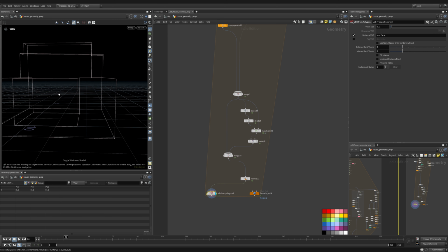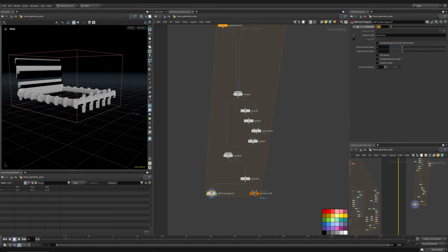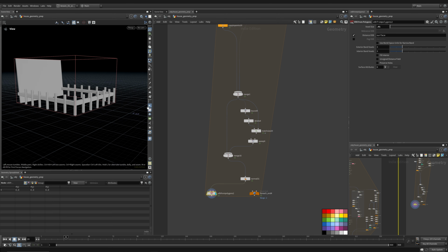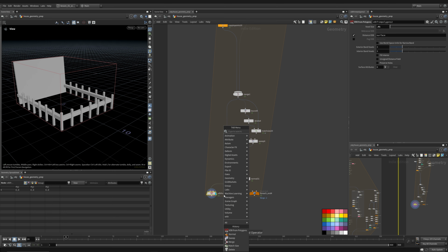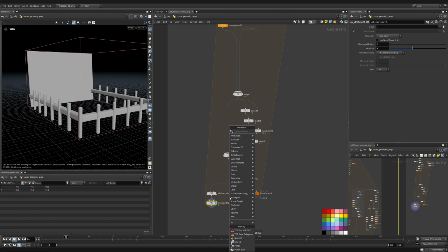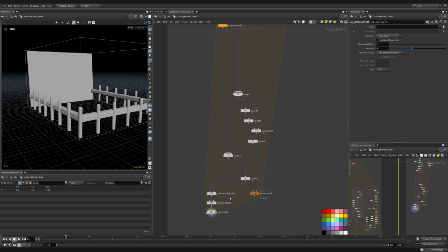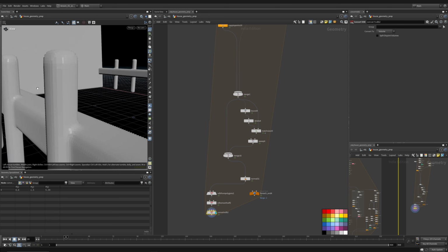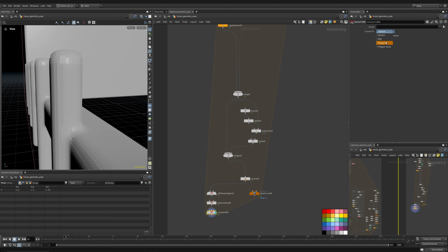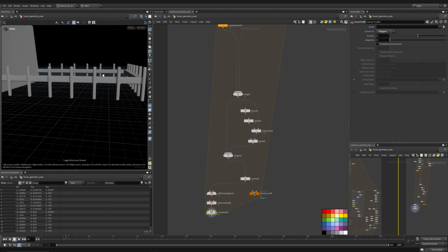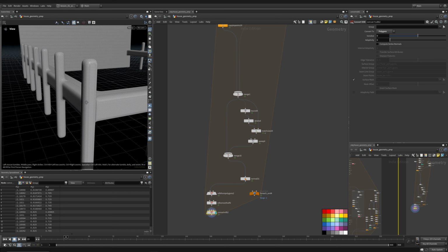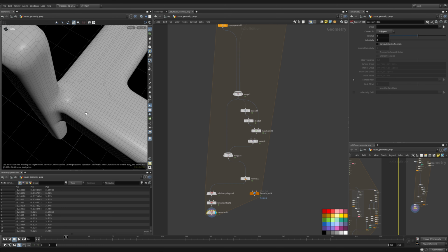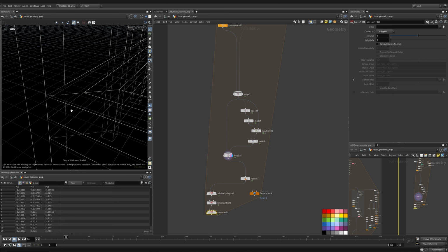This will create an SDF, which is the signed distance field. It's a type of VDB. But what I want to do is 0.01 maybe. We'll make this object here. And then if I do a VDB smooth SDF, I can smooth out this area, and then a VDB convert will let me convert back from an SDF, which you can see here is not actual geometry. I can convert from volume to polygons. And now you see I have these objects, and they're all nicely blended together. So there are these little smooth transitions between each of these objects, which we did not have when we were modeling.